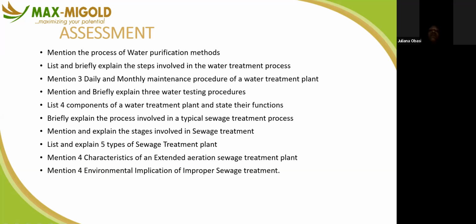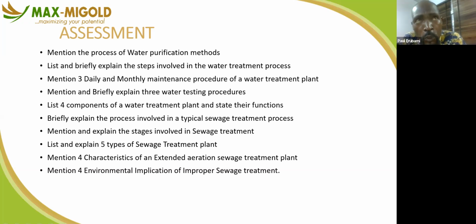Okay. Is there any software like that? Most especially when you do project work, before the plumbing system is put into operation, they always conduct what we call a pressure test. When they conduct a pressure test, if there is any point where there's going to be leakage, before they inject water into the plumbing system, it will definitely come out. They'll be able to rectify it before they do handing over.